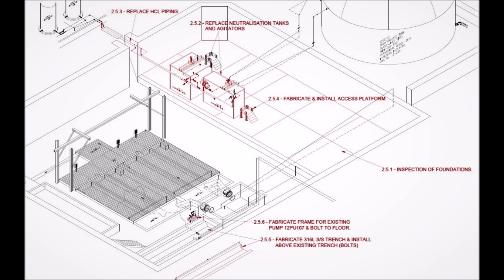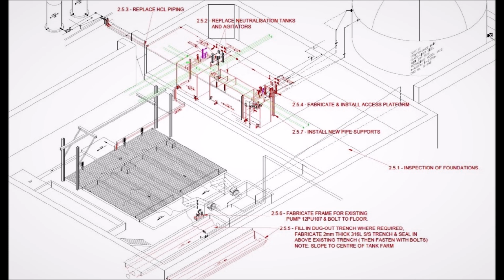Evidence of this in the project is shown here, with a preliminary definition from P&ID compared with a well-defined layout from survey, which identified additional requirements of piping route for access, replacement of pipe supports to enable lifting of vessels, replacement of piping to new vessels as existing flanges are old spec, along with additional work to dig out and replace the drainage gully at a lower level, as there is another system which feeds into this.